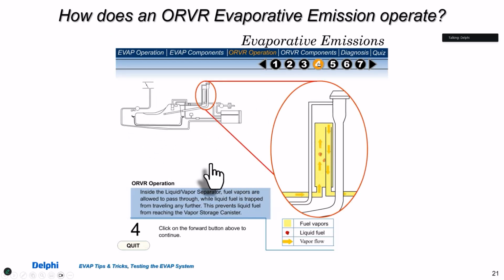I want to pause it here for a second, because if you're the type or you have customers that do this, they like to top it off. My rule of thumb is first click, I'm done. If you keep clicking it, what you do is you increase the level of fuel in this vapor separator. And if it starts going over the top, it gets into the canister and it begins to destroy the granulated charcoal that's porous in there, and it turns it into mud. That can become a restriction in the system, and we'll show you again at the end of a case study.